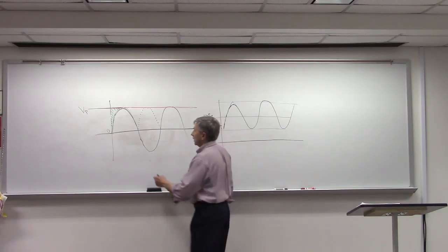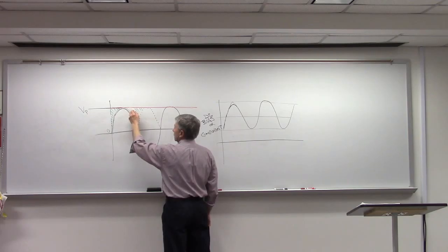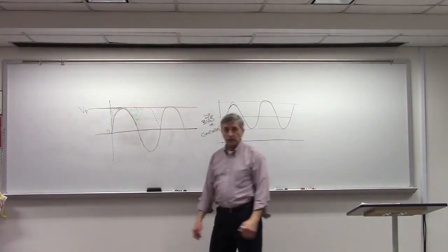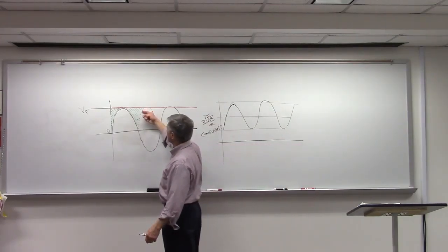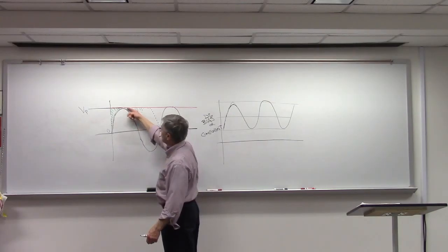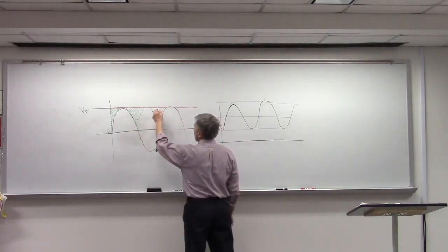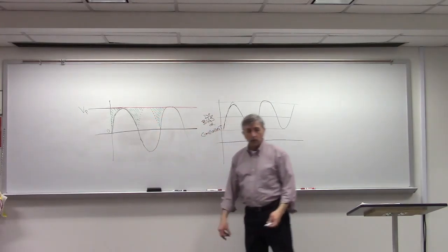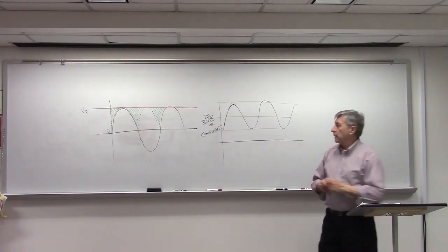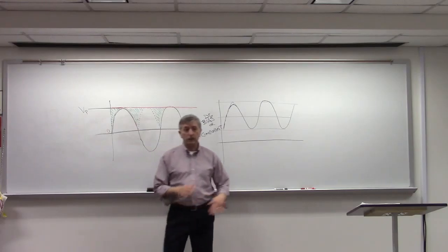So here the electrons are going one way, down here they're going another way, but they're still providing power to that light bulb. But if you compare the two curves, you're going to see that the light bulb being provided power from the direct current source is getting all that energy, and here in the AC source you got that big gap. Same way over here. So one light bulb is going to shine brighter than the other one, even though they both have the same peak value.